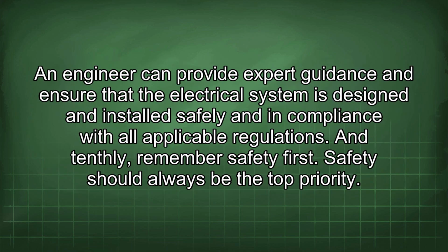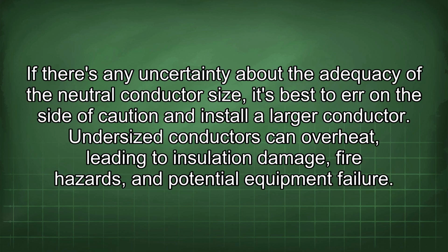An engineer can provide expert guidance and ensure that the electrical system is designed and installed safely and in compliance with all applicable regulations. And tenthly, remember safety first. Safety should always be the top priority. If there is any uncertainty about the adequacy of the neutral conductor size, it's best to err on the side of caution and install a larger conductor. Undersized conductors can overheat, leading to insulation damage, fire hazards, and potential equipment failure.